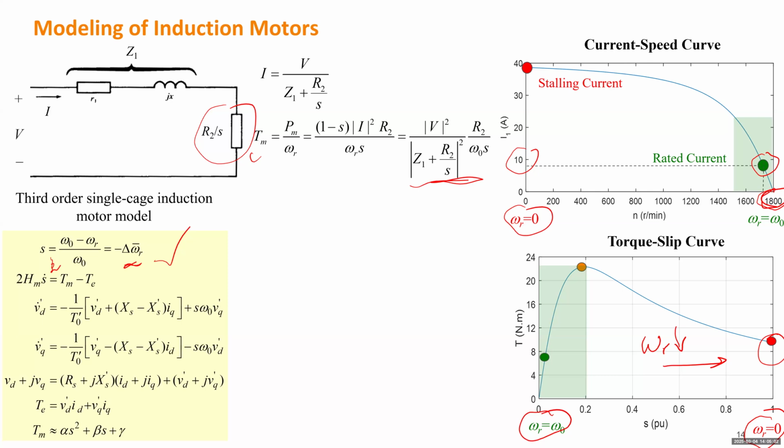And what are the next two equations? We use lowercase v because usually we call the voltage on the low side capital V, and for the generator side we use capital E. So the first state variable is called Vd prime. The second state variable is called Vq prime, which are two fictitious voltages in the D axis and Q axis of this motor. If you still recognize the two-axis model of the generator, those two equations are very similar to the corresponding two equations from the two-axis model.